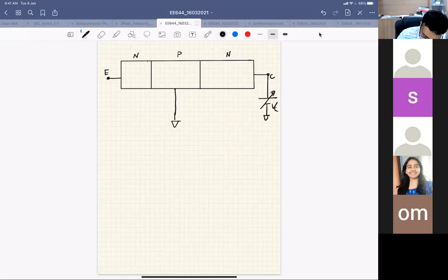But you could also give some voltage, let's say the emitter is not open. The emitter is connected to ground, and you give some voltage VBE, let's say 0.1 volt. That means I am forward biasing the emitter-base junction by 0.1 volt, injecting some electrons. Then if we go on increasing VC, these electrons are going through the junction also.